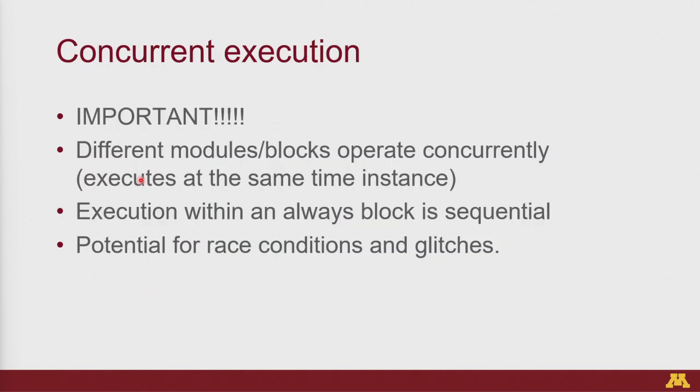Okay. One of the most important things which I tell everyone when they first get into Verilog is concurrent execution. If you have not come across a hardware description language before, you're very used to the fact that everything you write is a sequential operation, right? The first line of your code is going to be the first thing which is executed. That is plainly not true in Verilog.